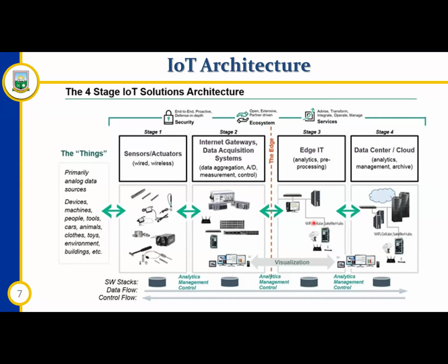And the example I gave was the temperature sensor. If it measures the temperature and it's 40, and after 5 minutes it measures it again and it's also 40, then there's no change in value. So the pre-processing happens and it's stored here. It doesn't push it to the cloud because the cloud already has the first data, which is the 40 degrees Celsius. But in a situation where there is a significant change, for instance, if it is 45 degrees Celsius, then we will now push it to the cloud.